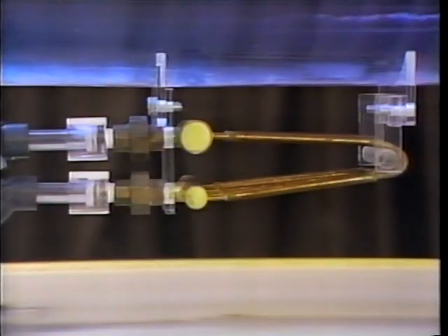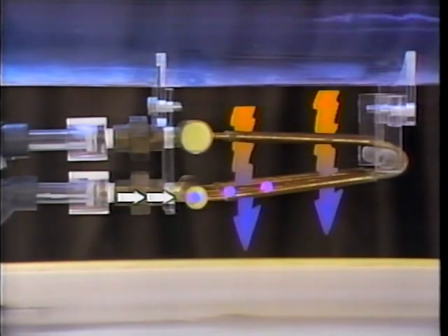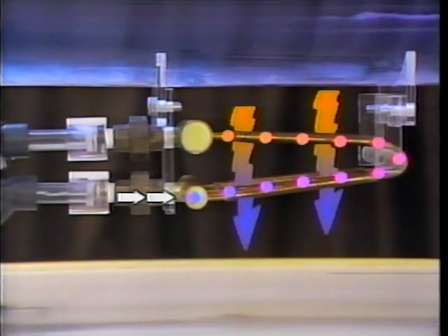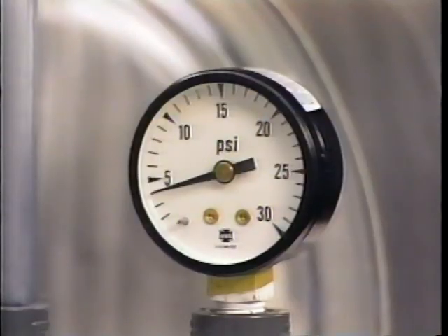This is accomplished by using the pressure building coil mounted on the bottom of the trailer. It works by converting some of the liquid to gas. This process is called vaporization. Heat from the air warms the extremely cold liquid in the coils, causing the liquid to boil and convert to a gas. Without this conversion, the pressure in the trailer would drop to an unacceptable level as product is withdrawn.